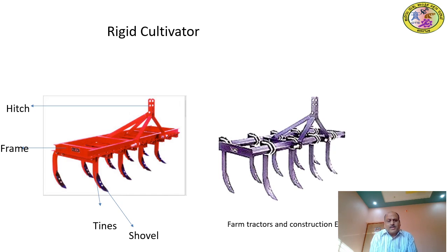So what is the disadvantage in this one? Whenever it encounters irregularities or any obstacles in the soil, there may be damage to the cultivator, damage to the tines, or the tines may break. For that purpose we use the spring loaded cultivator, which we will discuss later.